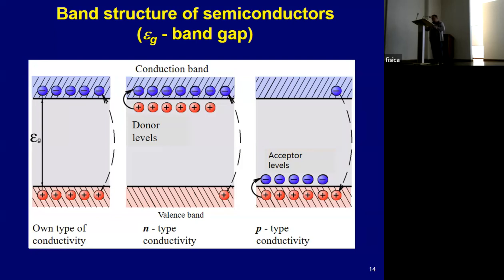The switching circuit of a semiconductor detector with the p-n junction is shown on the slide, and here layers p and n are separated by a transition region in which charge carriers are created under the action of ionizing radiation. These newly formed charge carriers are carried away by the electric field to the electrodes in a fraction of a microsecond. Silicon and germanium proved to be the most convenient materials for semiconductor detectors with a junction. The use of semiconductor detectors for measuring doses is limited by the noticeable dependence of the dose sensitivity on the radiation energy. There are some limitations.